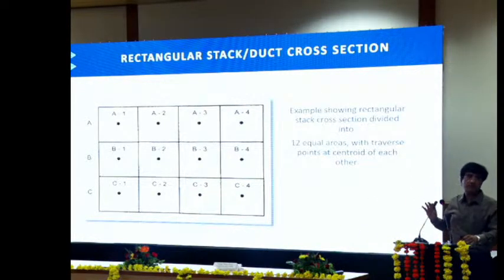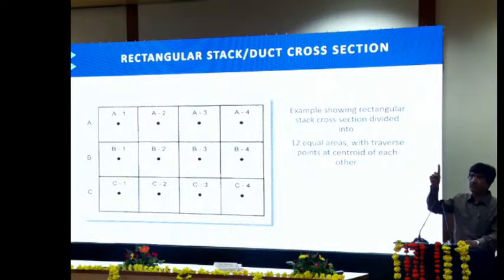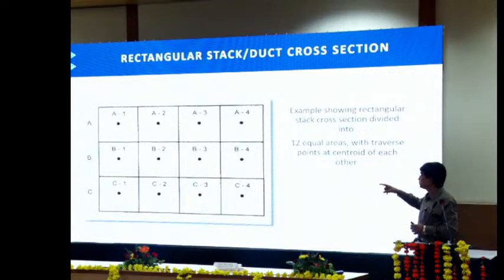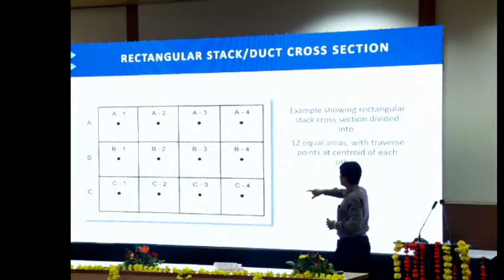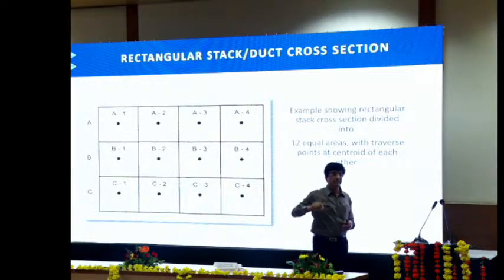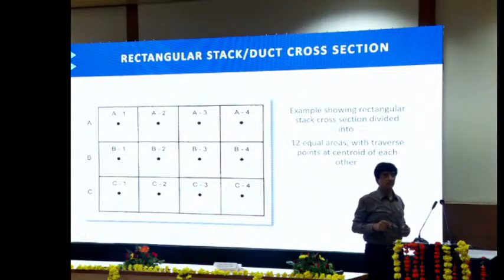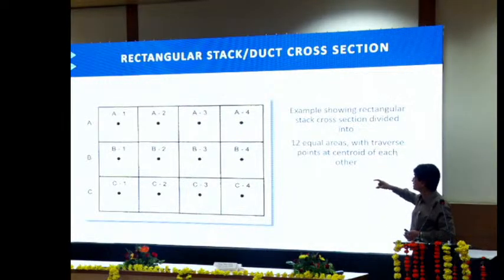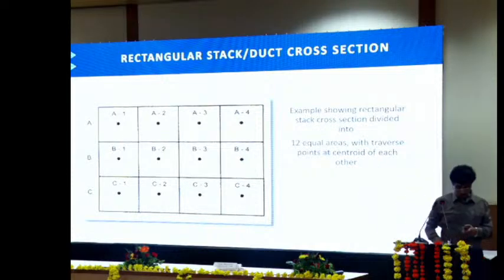Basically meeting these particular requirements. Because in most of the ducts, what we have seen is that there is only one porthole. Is it true? Yes. So the idea of doing this particular exercise is that you should be collecting the sample from various planes. Then only you can get the representative sample. Same way you need to put it from the top also sometimes. So the idea is that you are able to cover the whole of the duct.